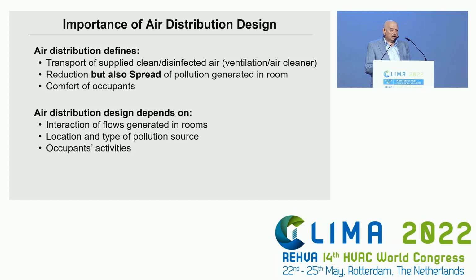And when we design air distribution, we have to consider several important issues. First, that in rooms there exists a complex interaction of flows, not only ventilation flow. There are buoyancy flows which are generated by occupants, by heated or cold surfaces and objects. And those may change in time, not only because occupants are moving, but also because outdoor conditions may change. Also, it is very important to consider the location and type of the pollution source